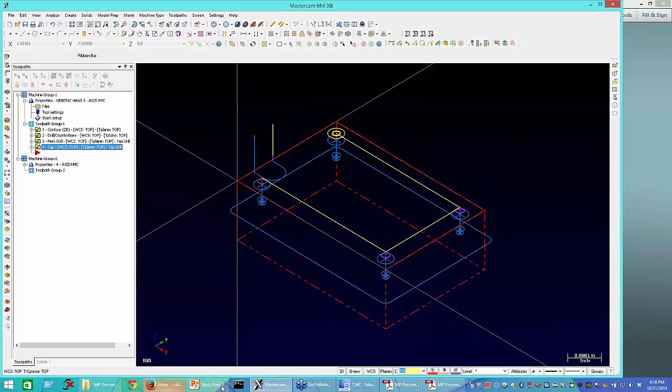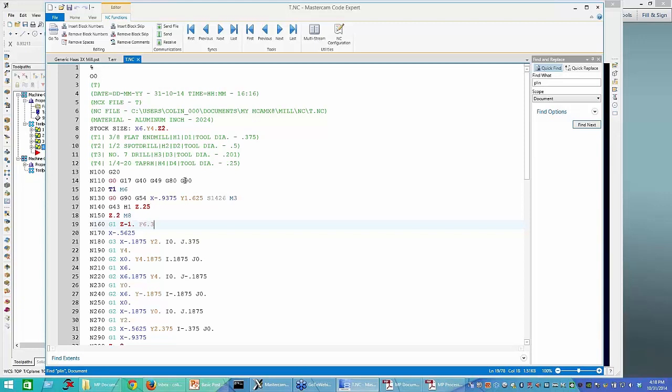Whenever you post in Mastercam, the post processor actually runs through your NCI information. Mastercam has what's called the pre-read loop, where it loops through the entire file, but it doesn't read everything. It loops through and reads the tool change info, for processing time's sake, where it skips some data and reads other data. And that's how it knows what's coming up. So how we can get our min and max X, Y, and Z extents for each toolpath, we do it in the pre-read loop.